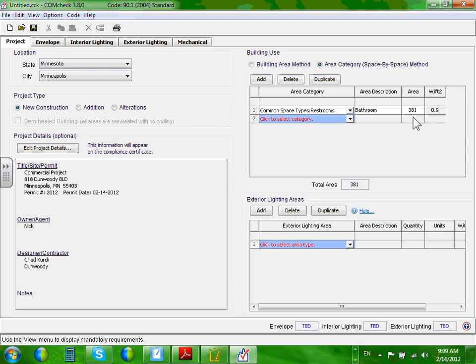For storage areas, the code doesn't list the bathroom, so to speak, but the smallest that the code goes is a warehouse, which is a quarter of a watt per square foot. So we're going to be comparing this one to one with the table. Any questions about this? You have to find the area, find the type of the area, and assign the square foot for this area. Thumbs up. Yep, we got that one.